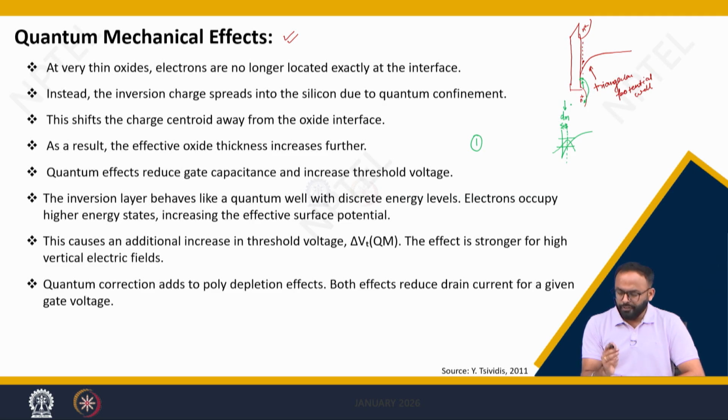If the charge is present away from the surface, the capacitance here decreases, and hence you can simply say the gate has poorer control over this charge. Thus, you need to model in such a way that this dm factor is incorporated.